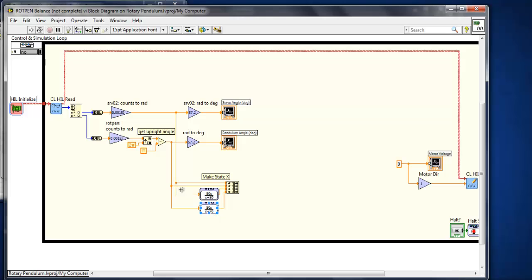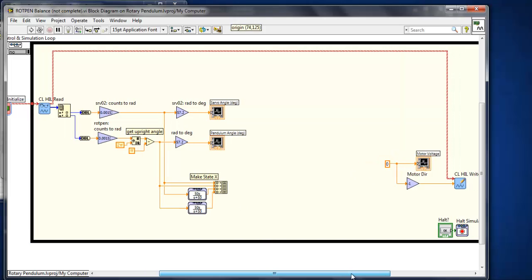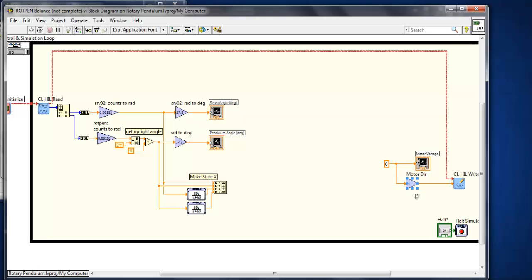So we're using basically a derivative with a low-pass filter with a cutoff of 50, which is about 8 hertz cutoff. And then on the right, you can see the motor direction convention to make sure that a positive voltage results in positive servo angle, and the rest is the same. So very similar to what we did in the second demo.